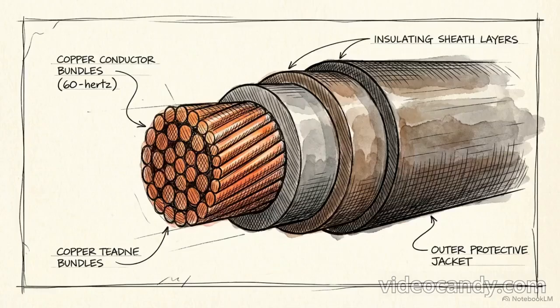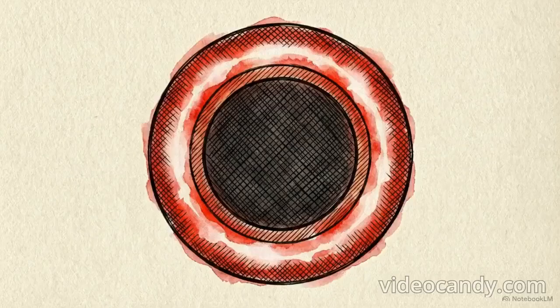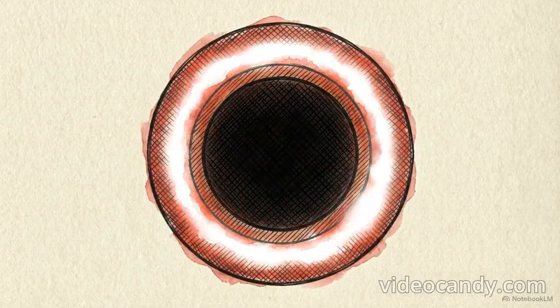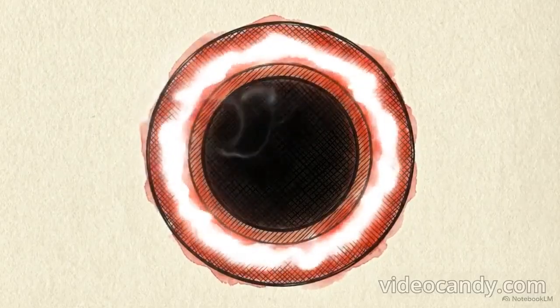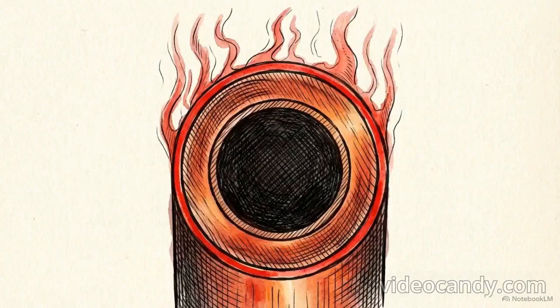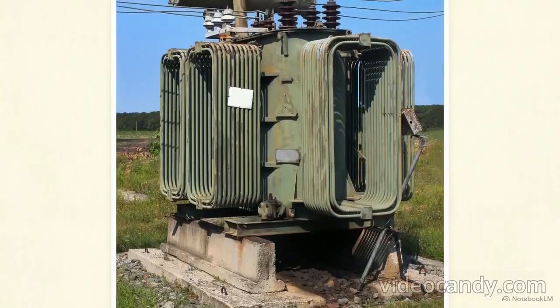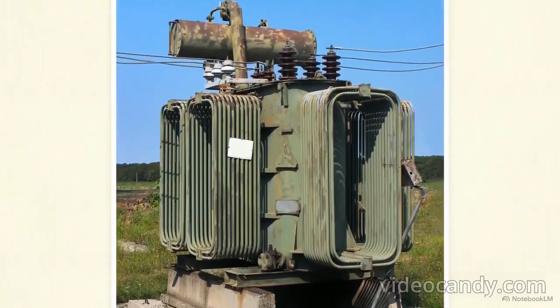Industrial equipment like transformers, heavy-duty circuit breakers, and thick transmission cables are engineered explicitly to carry 60 Hz power. They are not built to endure 300 or 420 Hz currents. As frequency increases, alternating current experiences the skin effect. The current is forced away from the center, crowding along the outer surface. This reduces the effective cross-section of the wire, increasing electrical resistance and generating intense heat.